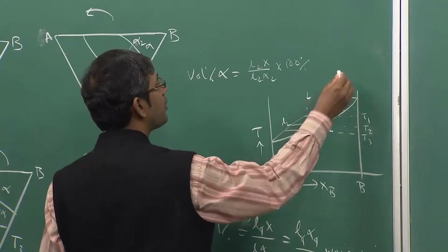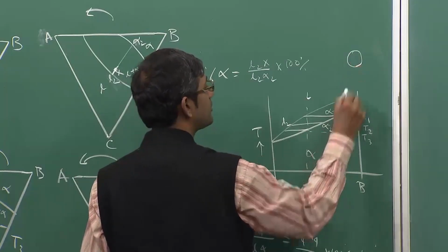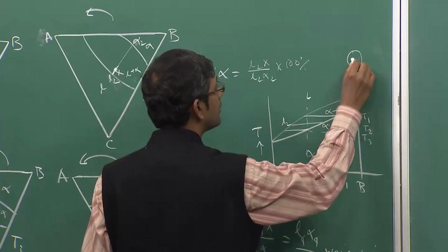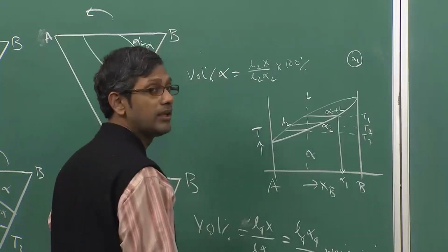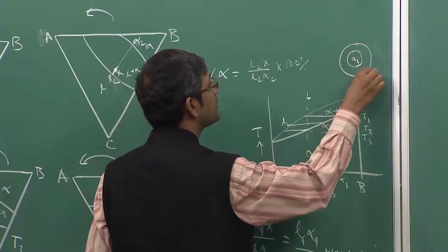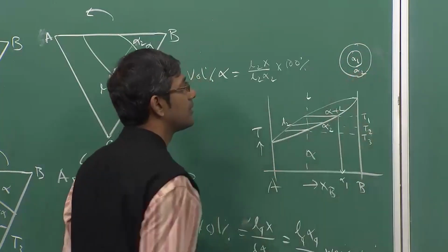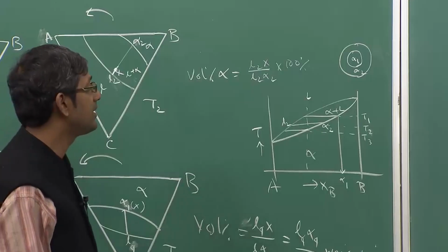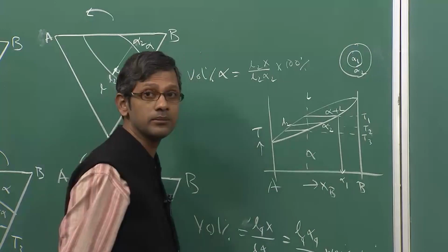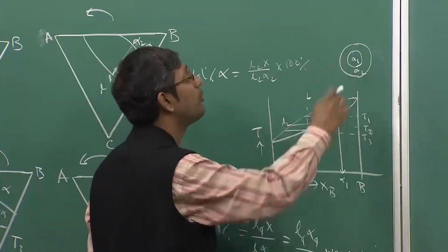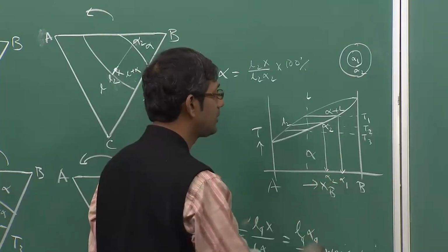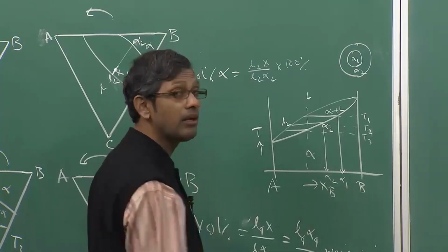So whatever solid I form at T1 will have a composition given by this point. Okay, so I write down alpha 1. As I cool it down from T1 to T2, I form another solid layer with the composition alpha 2, correct. So the problem in the non-equilibrium case is that you do not provide enough time for these two solids to homogenize, because these two solids have different composition, right. Can you see? Alpha 1 is richer in B than alpha 2.